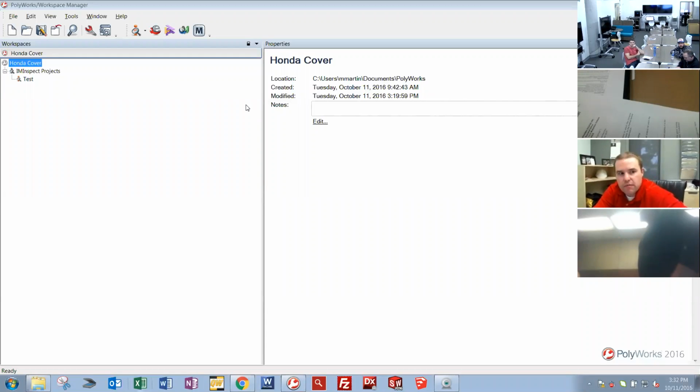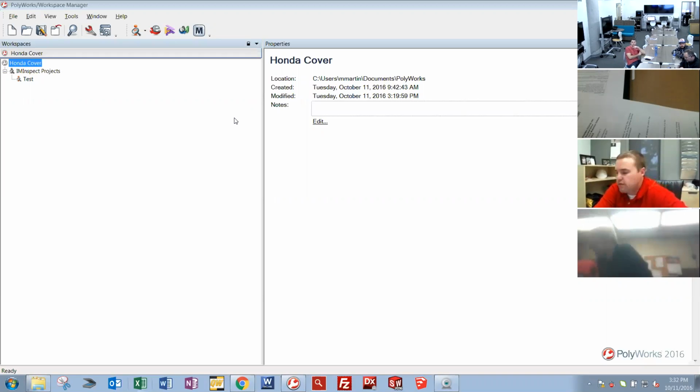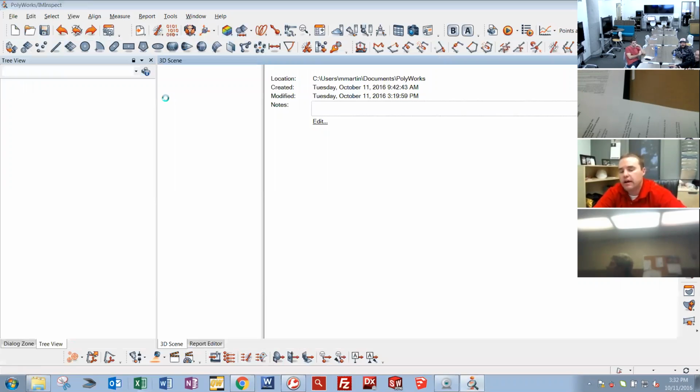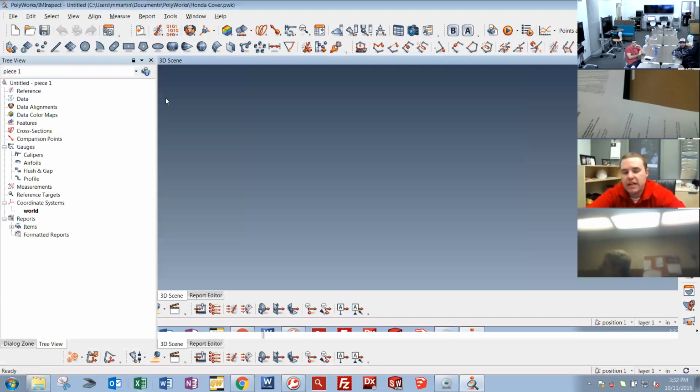My name's Matthew Martin from Exact Metrology, and I'll give a little overview of what Phil and Mike have probably hit on in the past two sessions, just to get us to creating the features. I'll open a blank IMInspect, bring in the CAD file and the STL, do a best fit alignment and a datum alignment, and then we can start creating features. I can show you some tips and tricks along the way, so shout out questions if you have them.